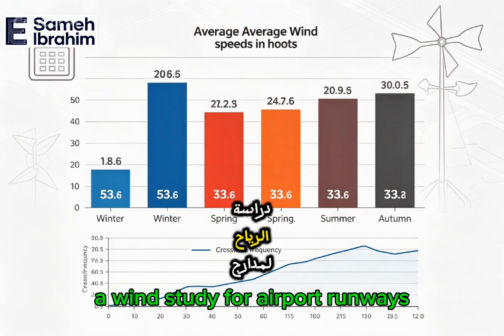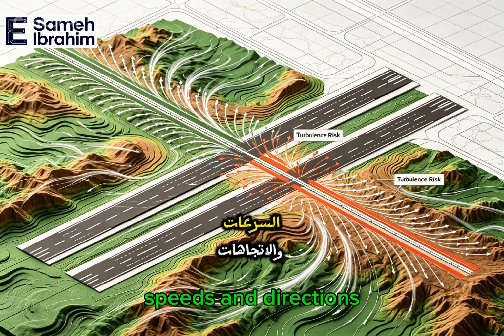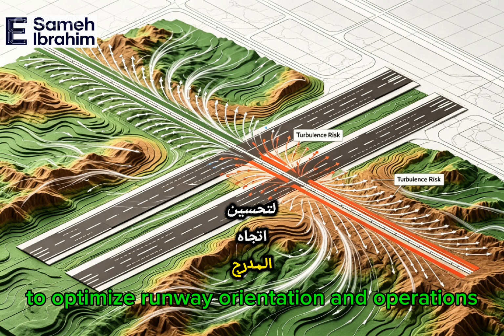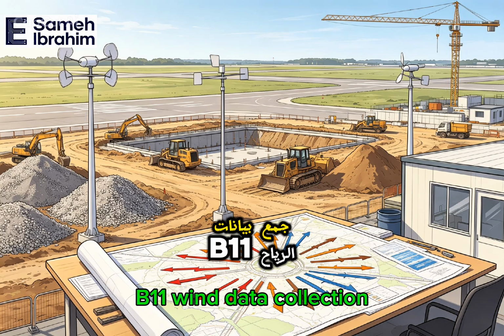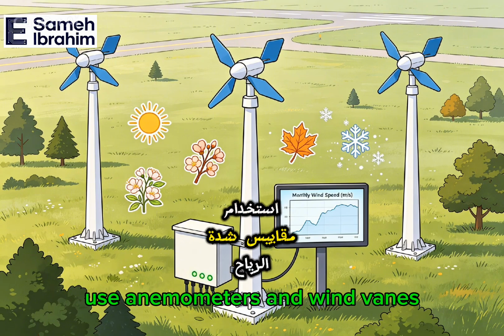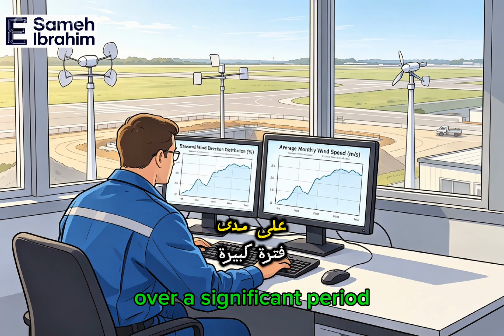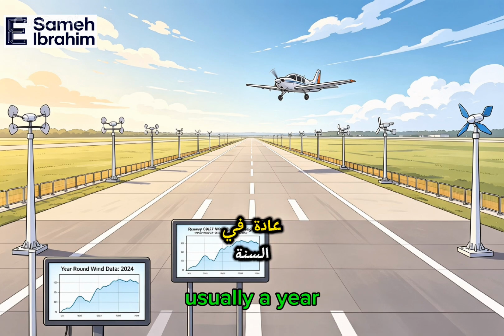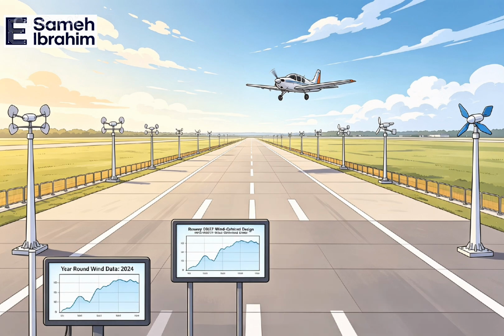B. Wind study. A wind study for airport runways typically involves analyzing wind patterns, speeds, and directions to optimize runway orientation and operations. Here are the key components. B1. Wind data collection. Use anemometers and wind vanes to gather data on wind speed and direction over a significant period, usually a year. Consider seasonal variations in wind patterns.